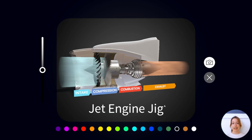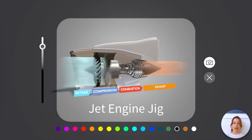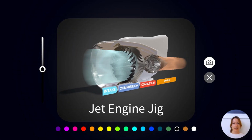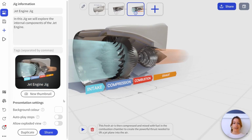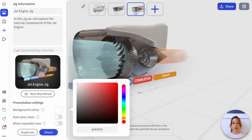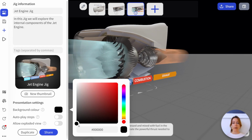I would recommend this as you can get a more dynamic shot by moving around this 3D space. In this case, I'm going with black as it provides good contrast against the jet engine, and this will be saved into our jig. Now in our menu we have a number of other options. We have the ability to change the background color of your jig scene. This will be visible when viewing your jig through the web viewer. If you had a lot of small white pieces, changing the color to black could help improve the contrast and your ability to visualize your 3D models.